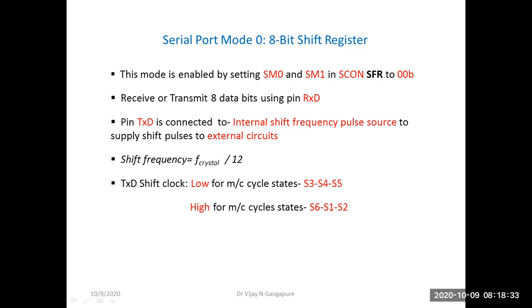So in mode 0, that is 8-bit shift register, we can receive or transmit data only on RxD pin, and in that case on TXD pin, a frequency pulse source is generated of frequency F crystal, or FOSC, divided by 12.